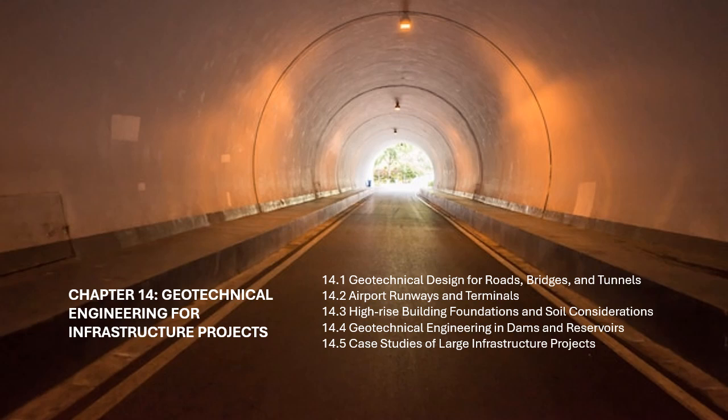Pavement structure design. Based on the subgrade's properties, the pavement structure is designed to provide sufficient strength and durability. This involves selecting appropriate materials for the base, subbase, and surface layers, as well as determining their thicknesses. The use of geosynthetics in road construction can also improve the overall performance of the pavement by reinforcing the subgrade and reducing settlement.